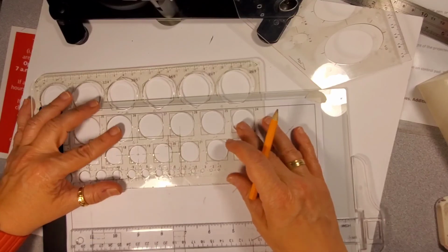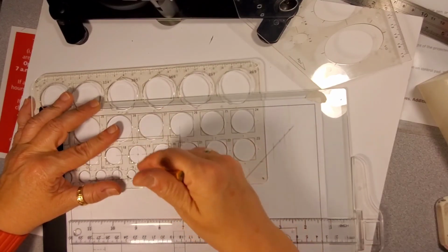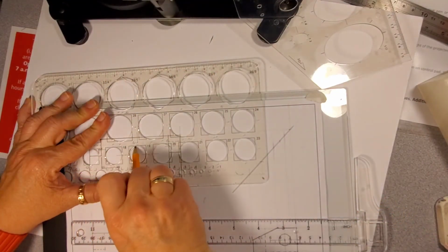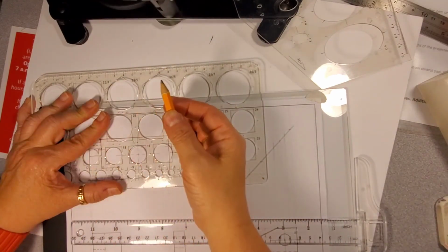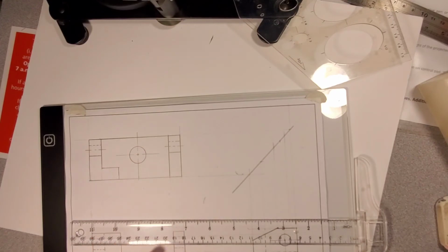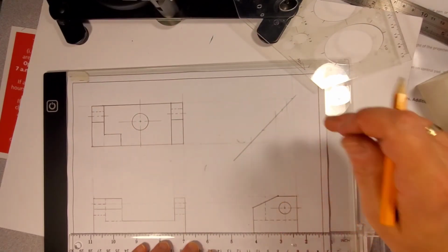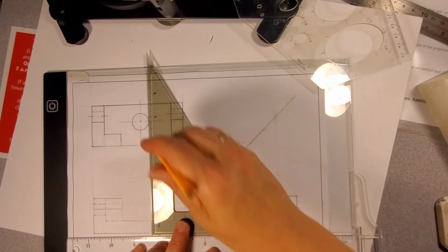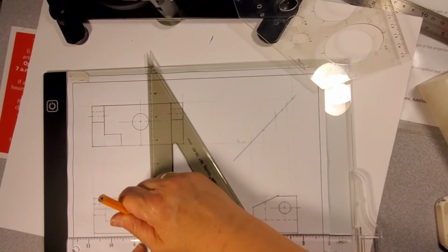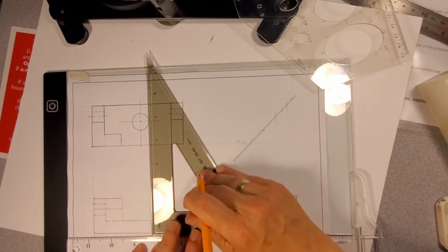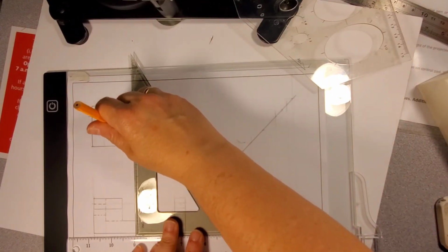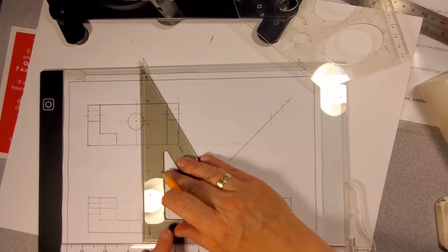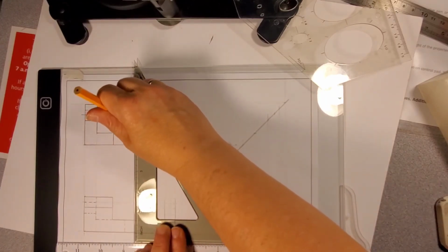So I pick that one, make sure my center lines are in alignment with the crosshairs. And again, I take my pencil, and you notice how I'm pointing it outwards because of the template and the thickness of the pencil. There you go. Now, you want to carry your line down, your hidden lines, right? Because I'm lazy, using the miter, the cheapest method I can. I haven't used the miter yet, I'm about to. So I've got my sides that are hidden lines, and I'm going to add my center line.